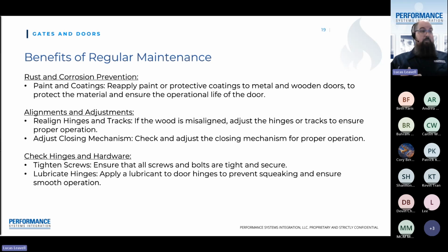And then I appreciate the question about the doors from the tenants, because hinges do need to be adjusted periodically. So there are 5 screws along the inside of a hinge for a reason. You do need to tighten them in order to adjust the angle in which the door moves at. If you don't do that, the door hangs, it pulls on those screws, and eventually will strip them out of the door frame itself.